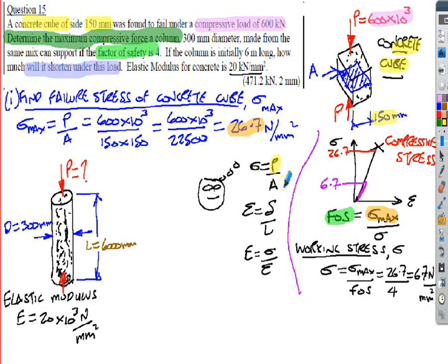First of all, what force can the column take, P? I can find that directly, because I'm given the diameter, so I'll be able to find the cross-sectional area, and I've just worked out the working stress that the column can be worked to, so I can find P directly using that equation, just a bit of transposition. That's not a problem.